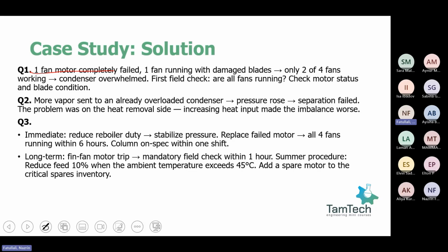Like not repaired, just sitting there failed for 3 days. No investigation occurred. They removed it from the system completely. But a second fan was also used with a damaged blade. It means that your airflow already decreased severely. So you just got 2 out of 4 fans actually working for 48-degree ambient temperature. The temperature is already high, and out of 4, you just have 2 working normally.